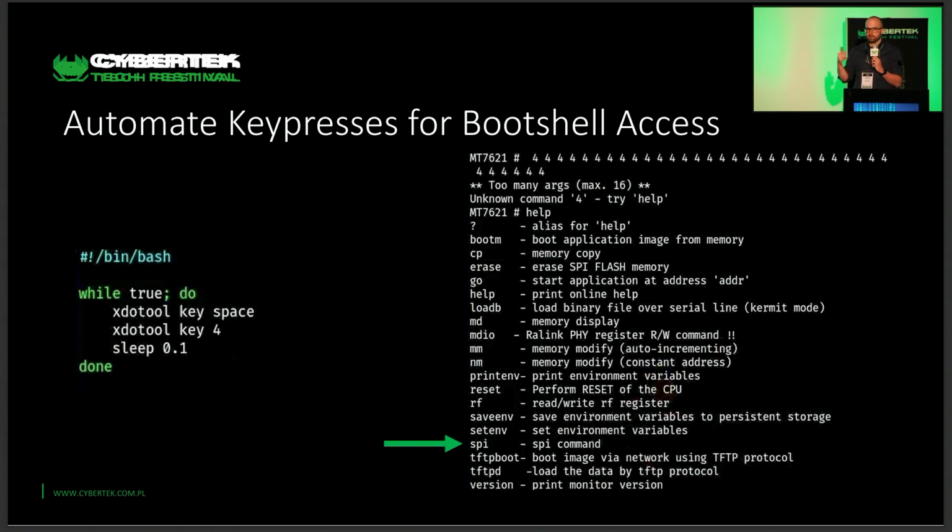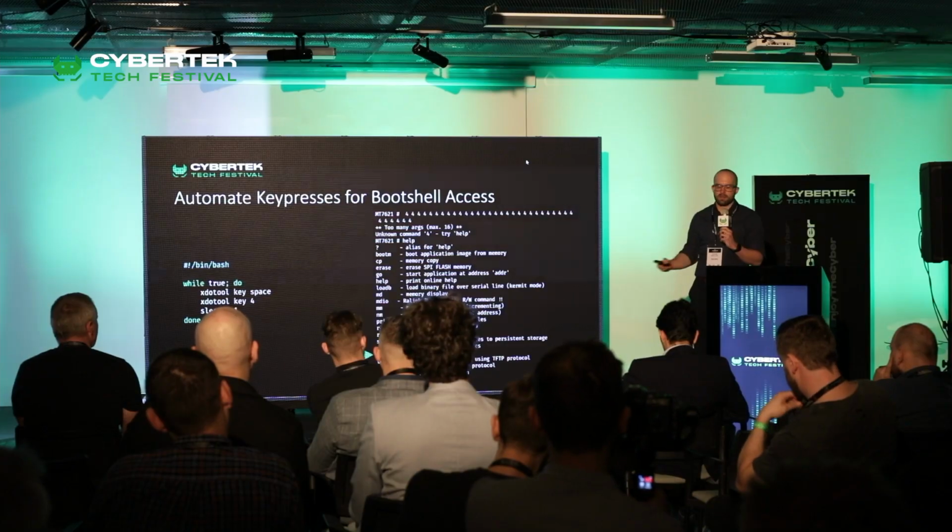At this point, most hardware hackers would go for the environmental variables because there you can set so-called boot arguments, which are passed from the bootloader to the kernel. And if you put a snippet of code in there to spawn a root shell, this would work on IoT devices, cheap home routers, but not here. If you manipulate the boot arguments, the checksum fails and it falls back to the defaults.